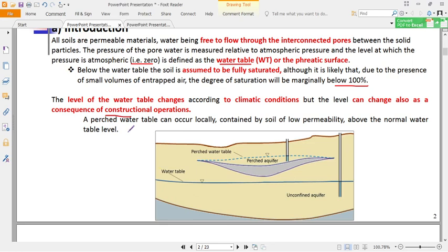But we also have to be careful. For instance, there are people who look for groundwater sources to supply water for use through digging of boreholes. When you are digging a borehole, you may encounter two structures: a confined aquifer and also what we call a perched aquifer. A perched aquifer occurs when, within a porous material, there is a deposit of clay.